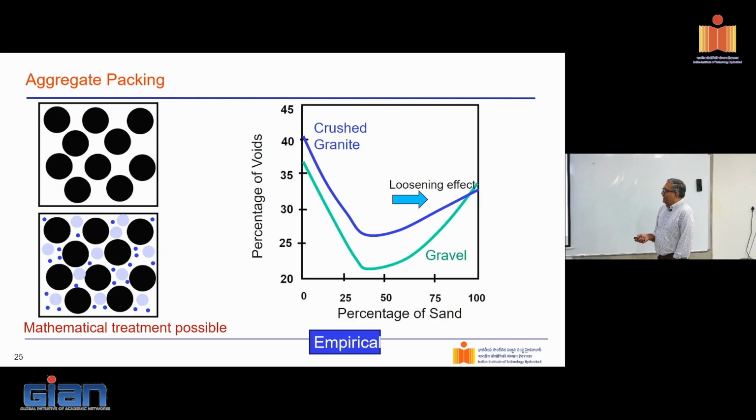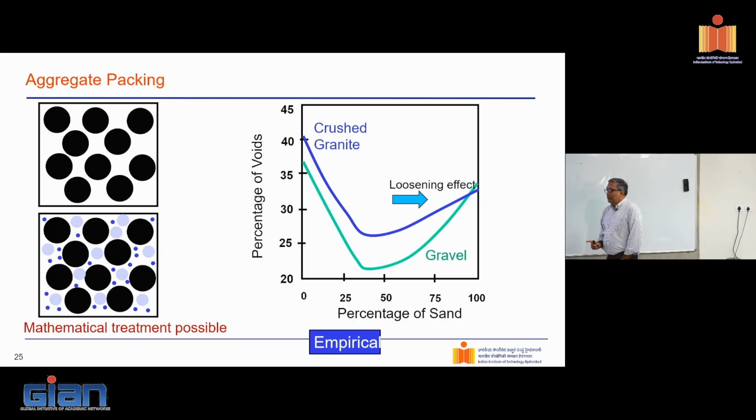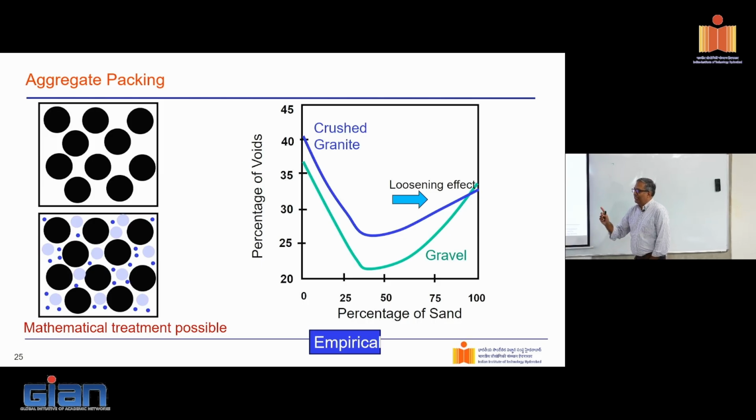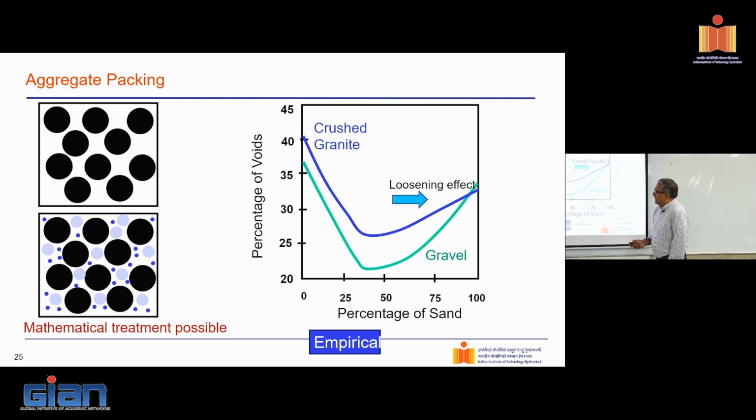Okay, so if I take, let's say, coarse aggregate and fine aggregate, again, whenever I illustrate, I go back to spheres, knowing full well that this is not reality, but the lessons I learn here can be ported into my real life. Now, what would happen if I try to pack coarse aggregate, which are well graded supposedly, with fine aggregate, which have their own distribution? Well, if I try to pack them up, I expect the smaller aggregate to go and pack between the gaps of the larger aggregate. And that's a winning game for me.